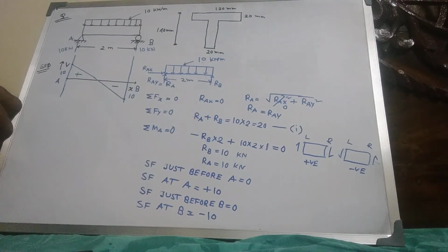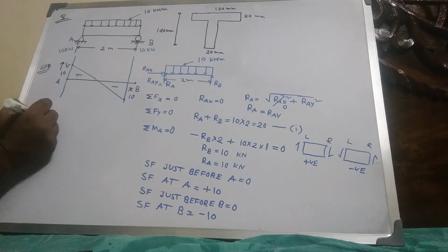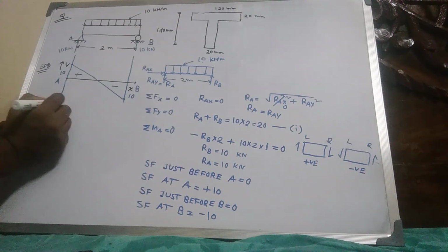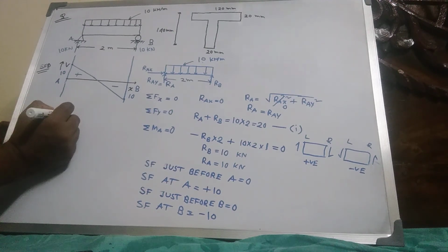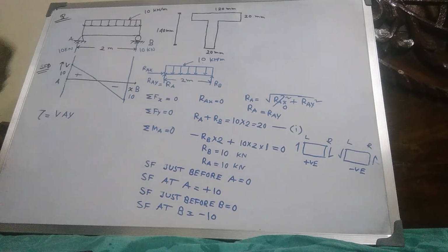So we can easily find it. We know shear stress equals shear force into A y bar, divided by the moment of inertia.